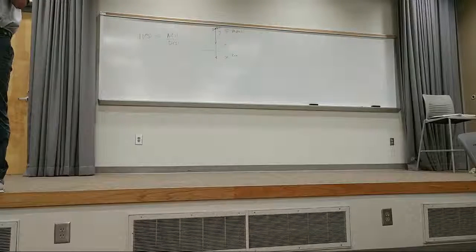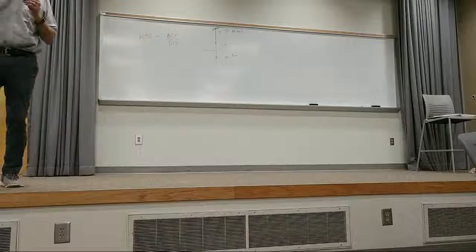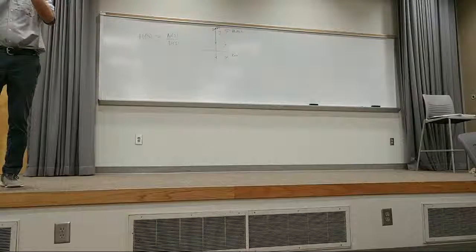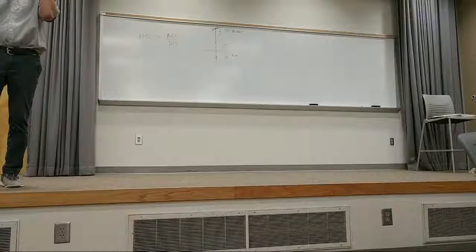Suppose I have an LC circuit in parallel. Now, you can do the math on this, but if I look at the impedance and write an equation for the input impedance, I'll find out that... well, let me take that back. Let me do it this way. If I have a series LC circuit, you'll find the impedance at resonance is 0, which means the current would go to infinity. And in a circuit like that, it would be unstable unless something limited the current.